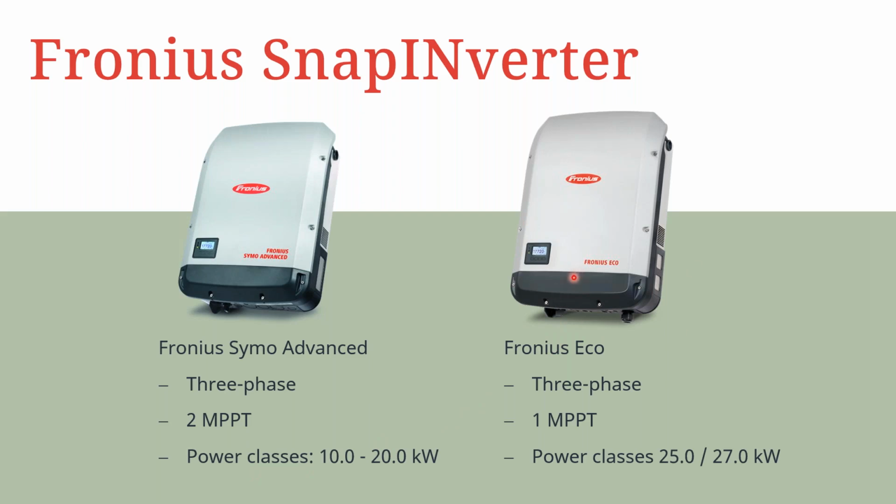We then have our Fronius Eco Inverters. Again, it's a 3-phase unit with 1 single MPPT, and this is power class rated from 25 to 27 kilowatts. You can oversize the Snap inverters, so it'll differ between the Simo and Eco range, for example, but you can oversize either one of the 2 inverters into the system.